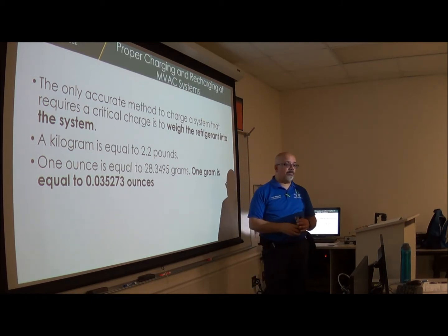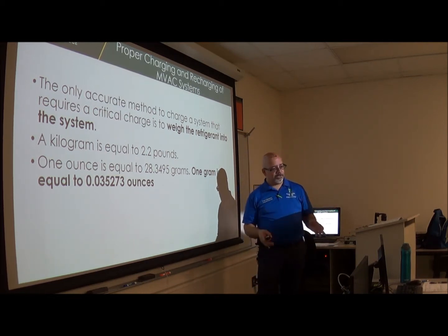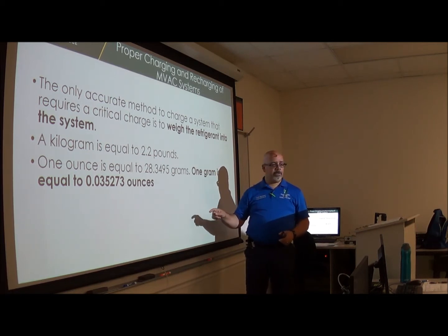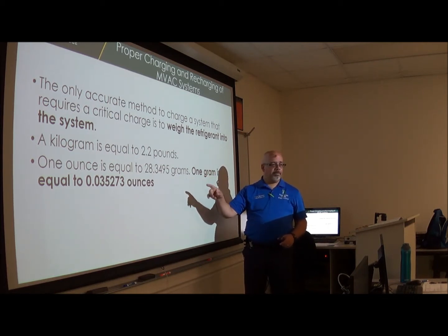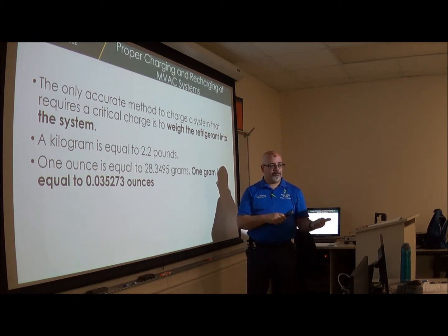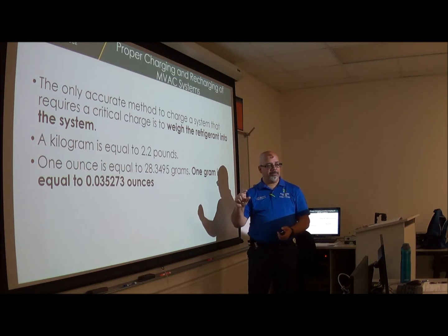So if you don't have a $15,000 recover recycle machine that you can just go in and put in this amount of oil and this amount of ounces of refrigerant, you'll need a scale. And you'll have to weigh your cylinder, see how much it's weighing, and then as you start putting refrigerant in your vehicle, you're going to have to keep watching that scale until it goes down that specific amount. And you have to know how to convert all that.